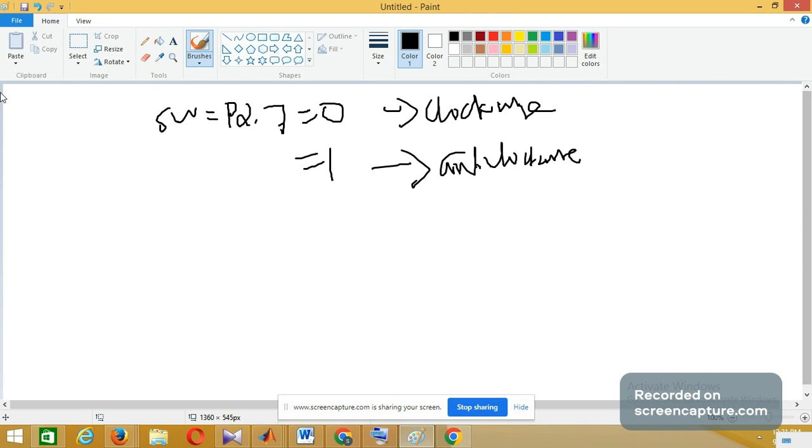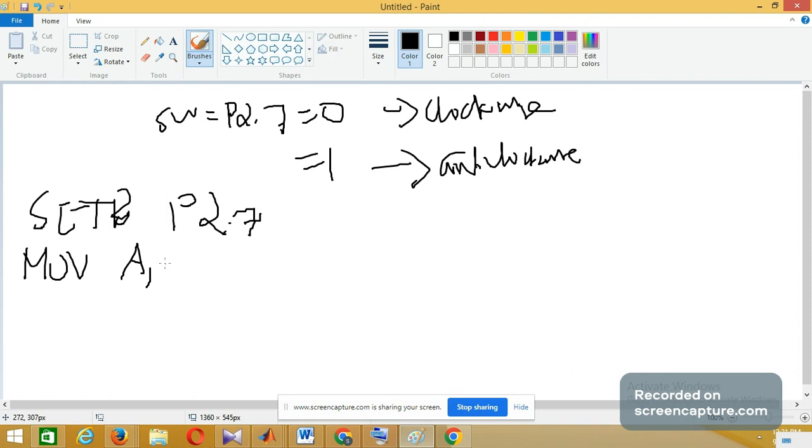So what you can do, there is an input port bit which is connected to the switch. So set that bit, it is connected to P2.7. So P2.7 is configured as an input port bit. Now give some value. For the normal sequence, you can give the value 66H. Now don't shift right or left here, because either it has to do clockwise, then right shift, or anti-clockwise, then left shift. So that you have to check, based on P2.7.